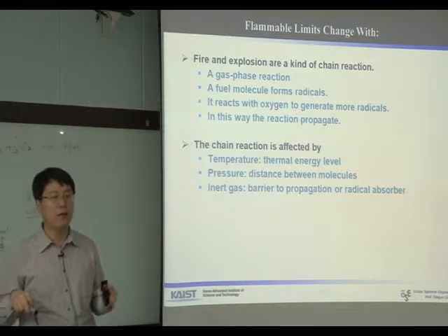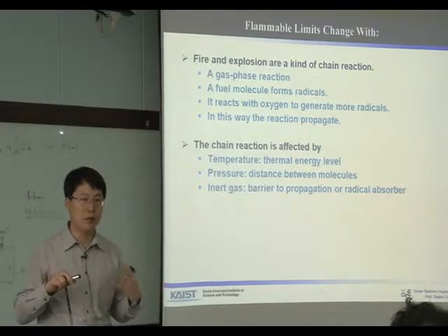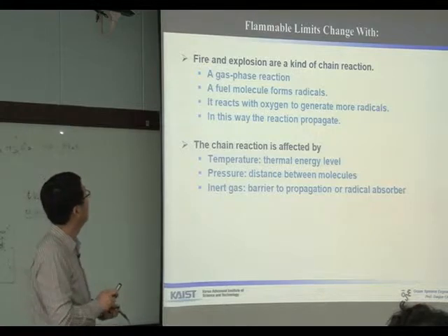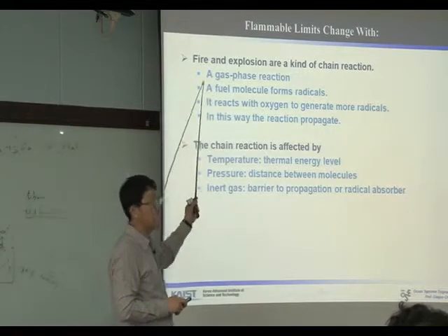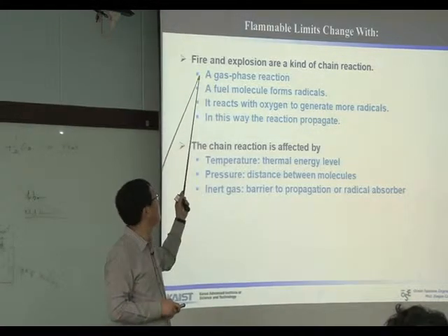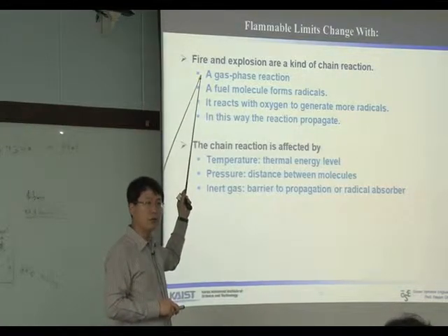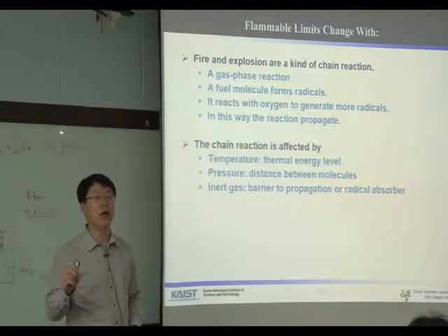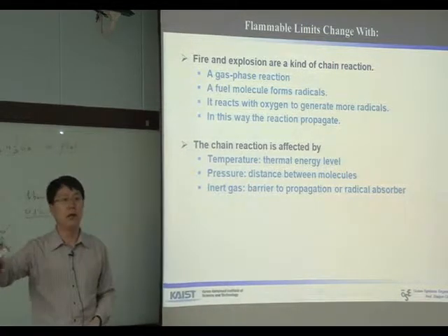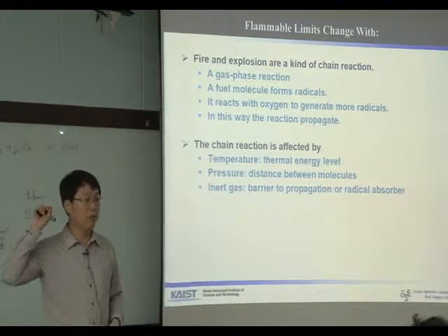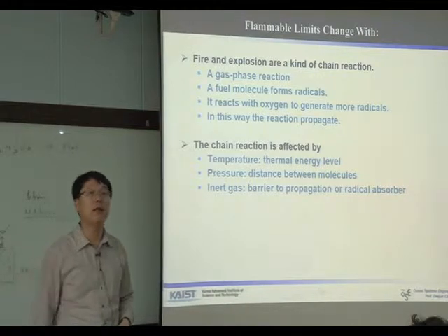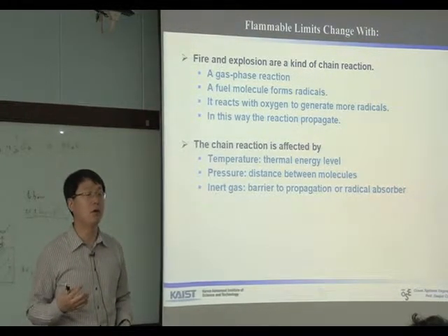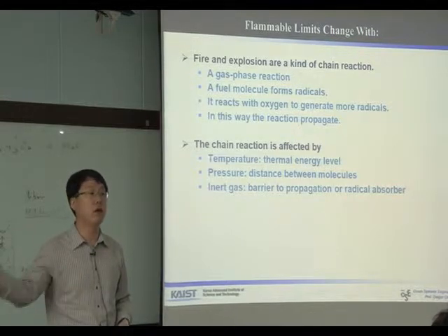Basically, let's think about the fire or explosion phenomena. Fire and explosion is a gas phase reaction. Do you agree? So even though we have LNG here, if we put the flame into the LNG, nothing happens because we don't have enough vaporized component here.